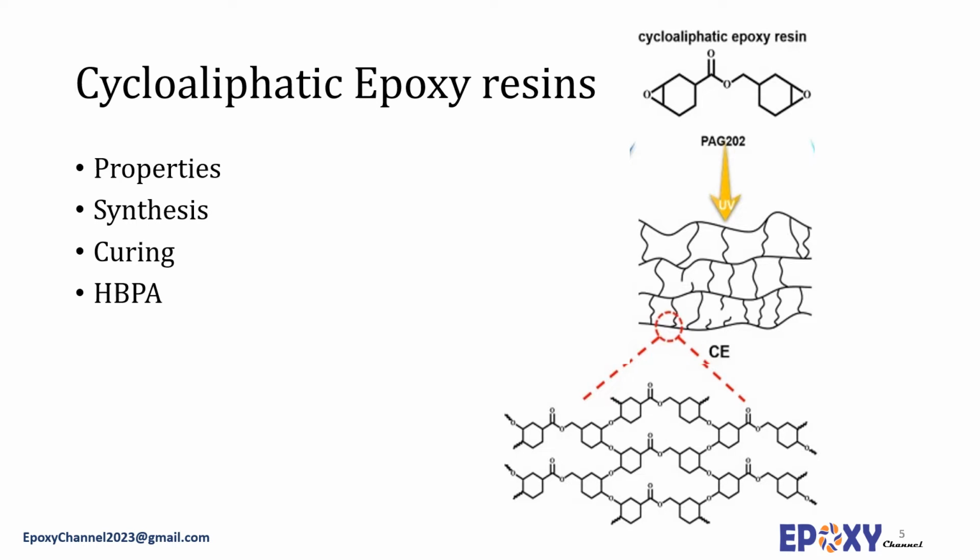These resins contain one or more cycloaliphatic rings, and as epichlorohydrin is not involved there is no chlorine, which makes these resins suitable for electrical and electronic applications, where the absence of chlorine impurity is of great importance. It should also be mentioned that these rings are saturated.